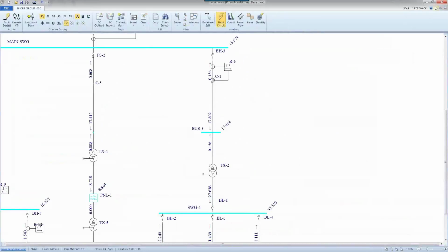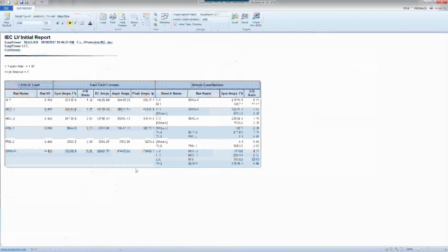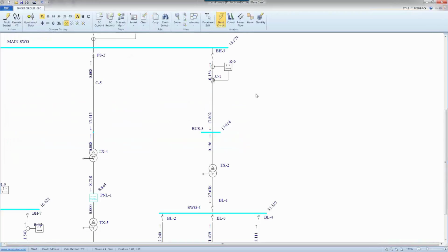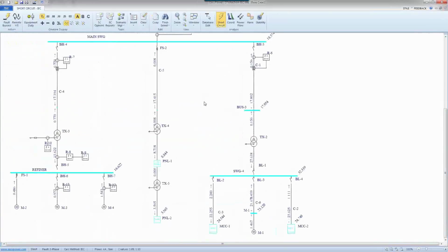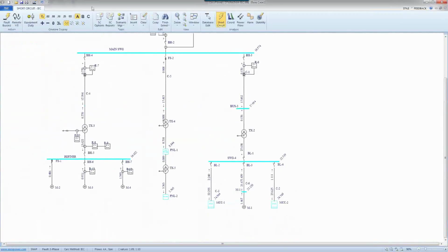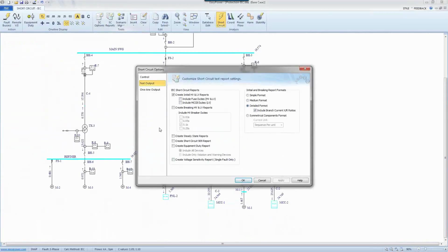I go to the other report here, which is for the low voltage. Again, the maximum C factor is given, and the peak value is method C. Every detail is laid out here. These reports are an excellent source of information when it comes to really analyzing your system. We have tried to cover every possible angle, every possible value that you might literally need when you perform a study. I would say that hardly any report or anything is missing from this combination. And again, a lot of them are new.